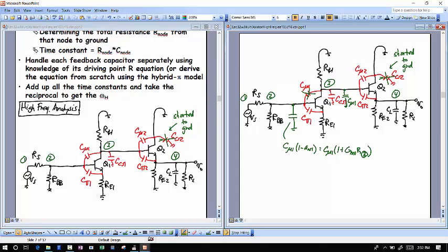You've got a lot of gain from B to C. From B to E you don't have much gain; B to E is going to be gain less than 1 if you've memorized your equations, which is why memorization is extremely important. So this C mu 1 is exactly where the Miller effect is most applicable. You have gain from B to C, so I'm taking something in feedback, breaking that feedback, and just having shunt values at those nodes. You should review the Miller material, and you'll see that what I'm doing is exactly what we went through in that other lecture.